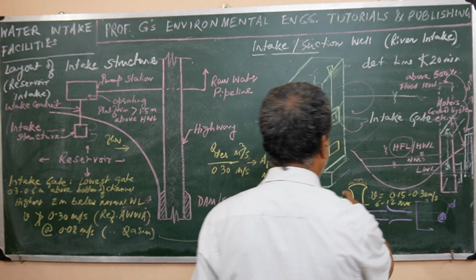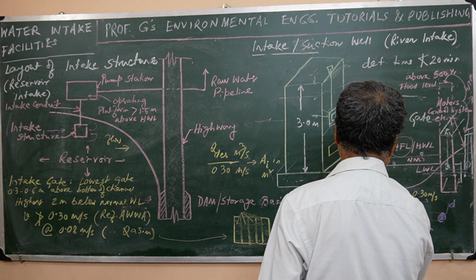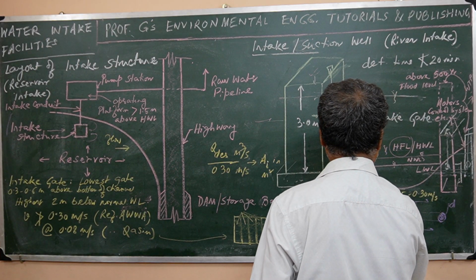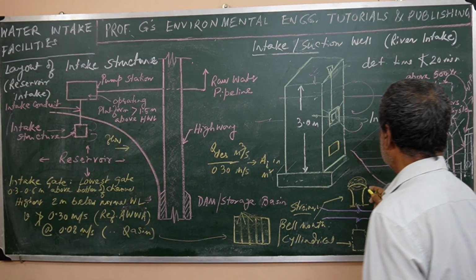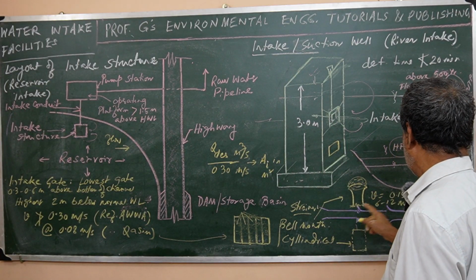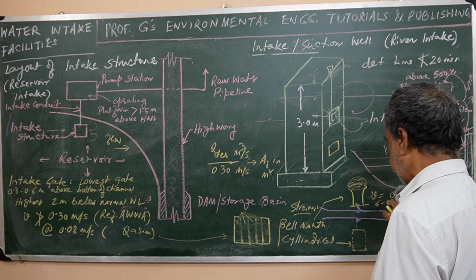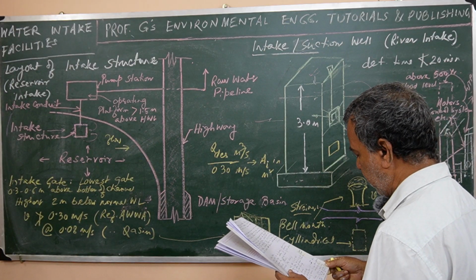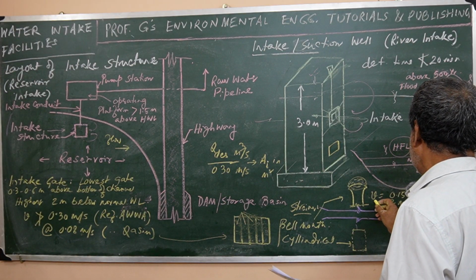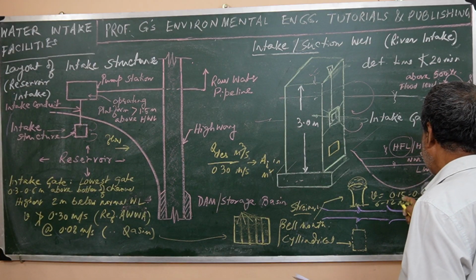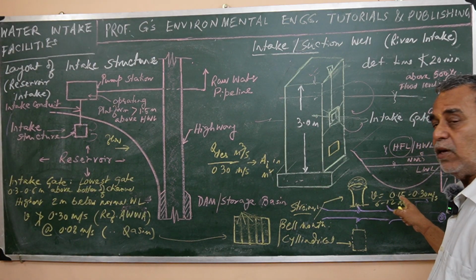and when you calculate the total strainer area, that actually will be 2 times the opening area, 2 times the effective area. So first you will calculate your effective area, based on this velocity.